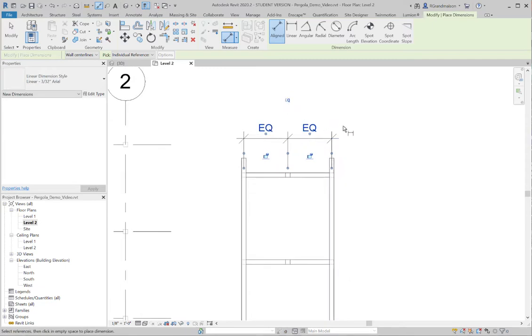If you have a problem like that where something moves where you don't expect it to, a couple of things you might consider is redoing the dimension and making certain that you got the right thing you expected to align and lock to or dimension to. The other thing you might try is pinning the things that you know shouldn't move. So I could have potentially tried pinning that post below to keep it from moving, or the end of that. Those are a couple of techniques you might think about using.